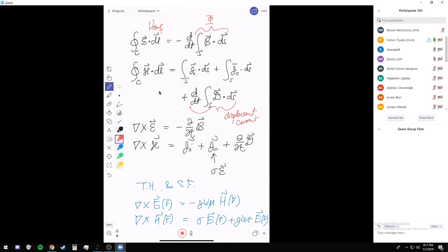And if I give you a simple circuit that has a capacitor, and I give you the material property, I can ask you how much current is flowing through that capacitor. I think we looked at one of the quiz questions. Make sure you understand those quiz questions, right? If the material between the two plates of the parallel plate capacitor is a perfect dielectric, then you only have displacement current. However, if the material has slightly some loss, in other words the conductivity is not zero, then inside that capacitor you will have both conduction current and also displacement current, right?